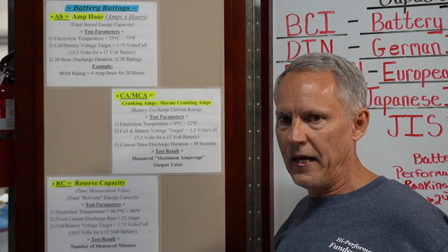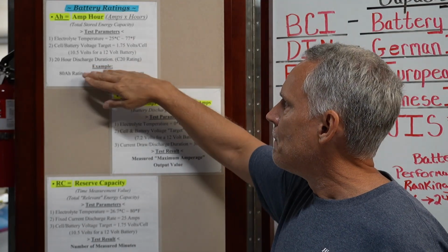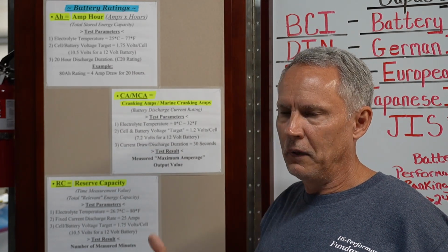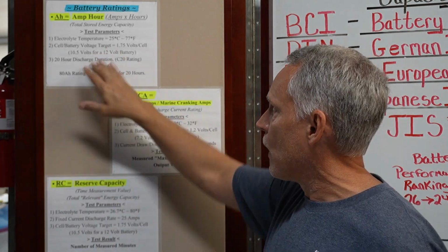I mean, not totally dead, but to a point where below about 10.5 volts it becomes battery damaging. So you don't want to run it below that. So anyhow, that's your amp hour rating.